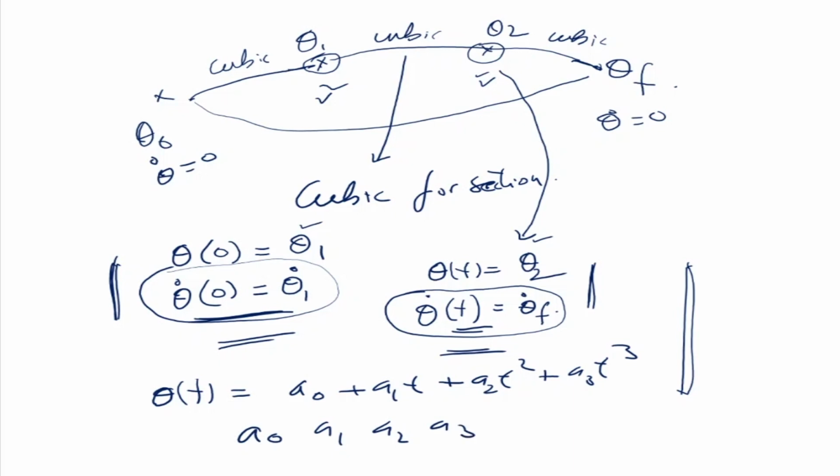So what we have seen today is trajectory planning for a manipulator going from start to end, without a via point and also with a via point. Now when we have a via point, we need to choose the velocity at the via point. So what is going to be this velocity and that velocity? In order to choose the velocity, there are 3 ways.